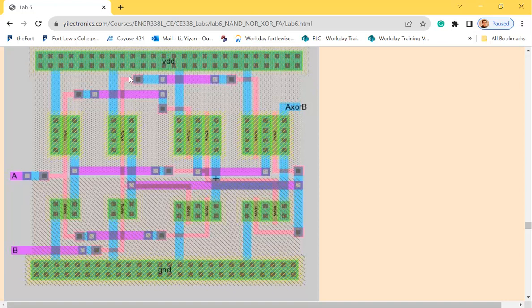Make sense? See here, I need to connect this gate to this gate. Instead of directly using a poly layer to draw a pink trace, I did so many things to it. It's just one simple connection, and you can see I put in the effort to avoid using a lot of poly traces.